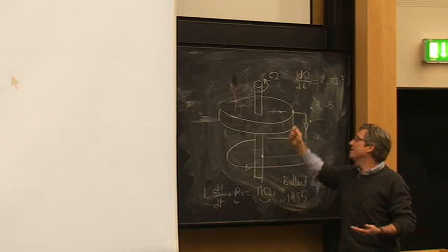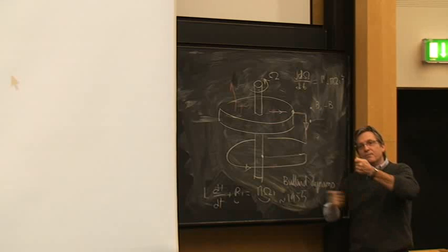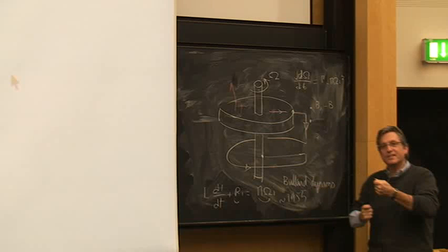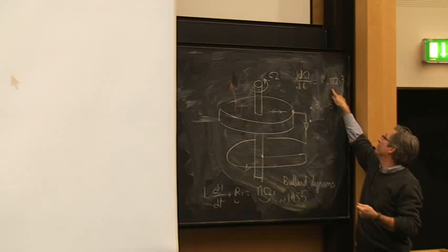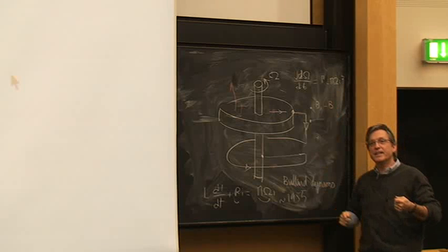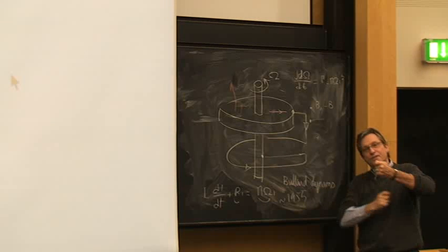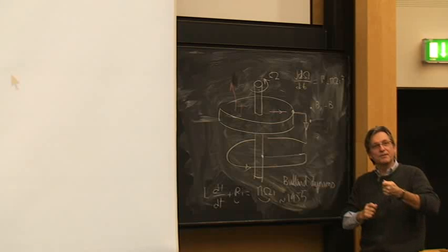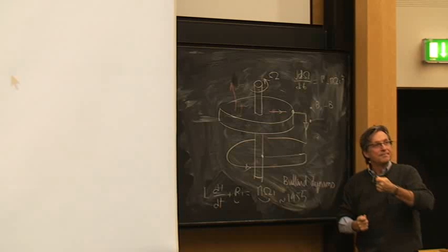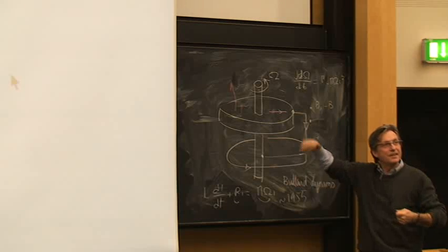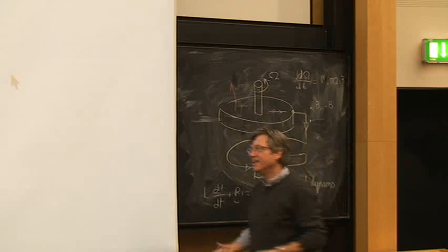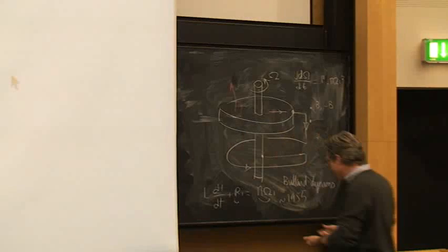Because the torque will buy you some velocity, but the velocity reduces the torque, so the thing is slowing down, the magnetic field goes down, the braking torque goes down as well, and the thing speeds up. And you get oscillations, you get all kinds of behavior. It's a fantastic example.